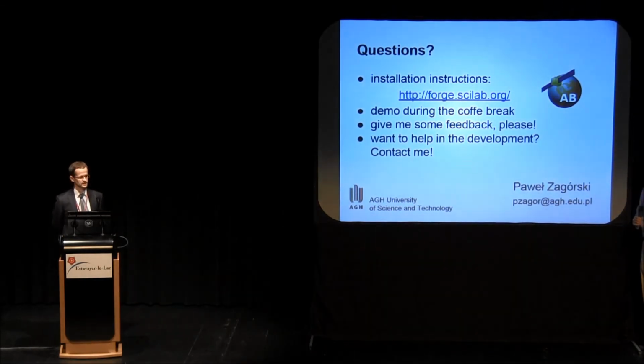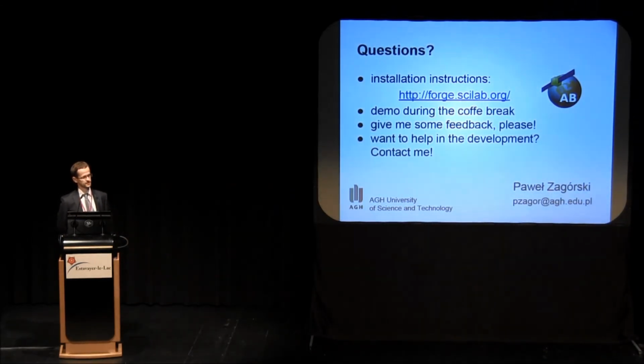Okay. The blockset, and Xcos itself, has probably most of the mathematical functions you need. You would have to make a diagram that does that. So the things that you will be helped with, you will have a block that instantly calculates sun position. You will have a block that calculates your satellite position. You will have a block that calculates if the satellite is in sunlight, so Earth eclipse. And as for solar panel efficiencies, you would have to create your own model as you would do it in Simulink. Okay, great. Thank you very much.